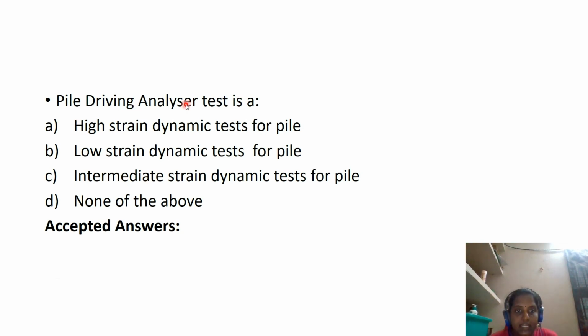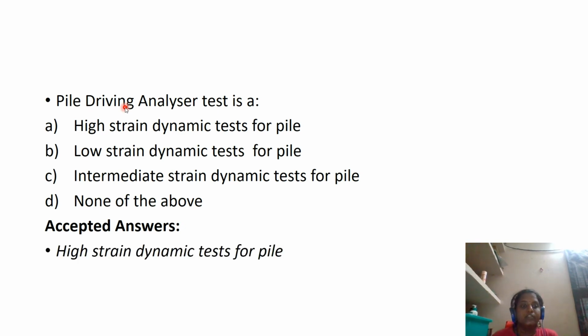Pile driving analyzer test. As I said, the pile driving analyzer, whether it is going to be a high strain or a low strain. So in pile driving, we are going to drive the pile. Obviously, the force that you are going to apply is going to be very, very large. So it is going to be a high strain dynamic test.